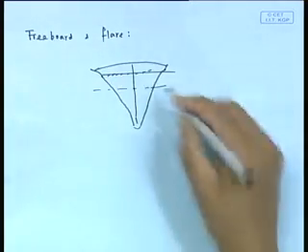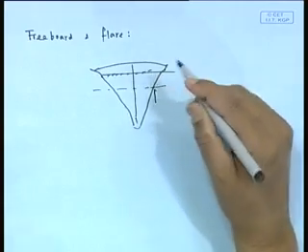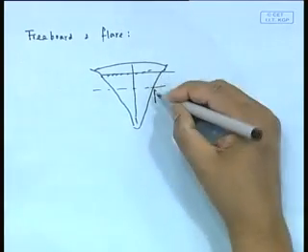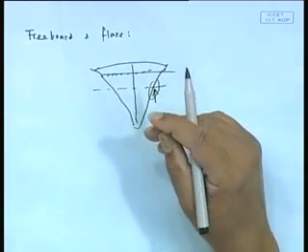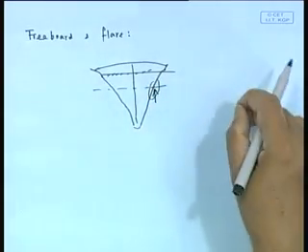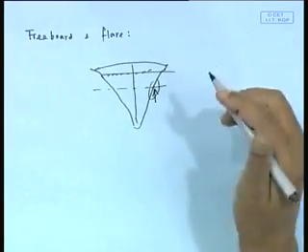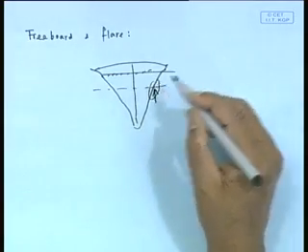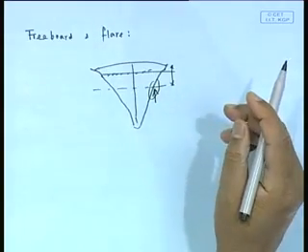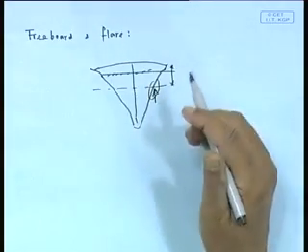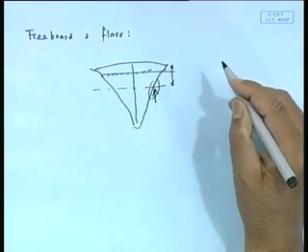Now, the point is that an increase in flare normally will increase the slamming. That's obvious, especially flare slamming, what they call slam at this region. This is also connected to your so-called U shape and V shape. On the other hand, freeboard by itself doesn't generally have much effect as far as the section shape is concerned.